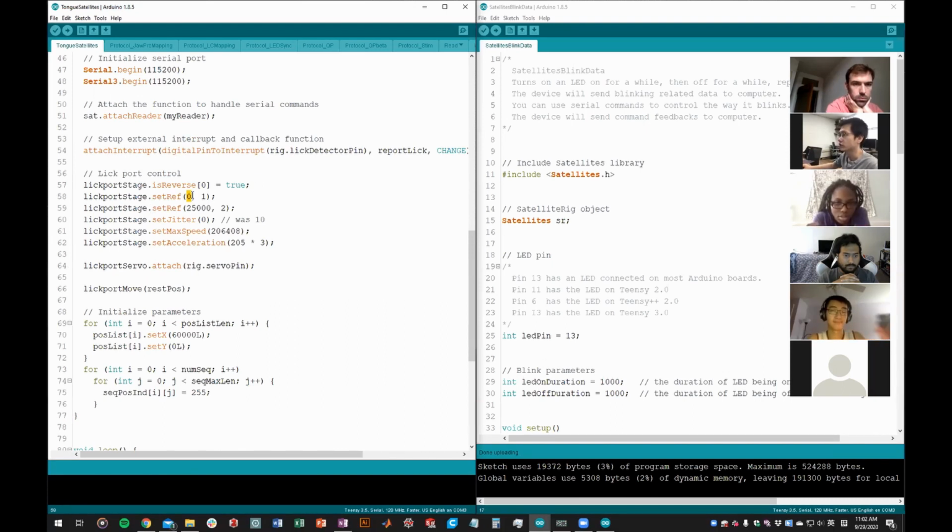Here is the reference coordinate for the first axis, which is the AP axis, and what is the reference position for the lateral axis, which is the second axis. So here, the second axis in our rig is 5 centimeters long, which is 50,000 microns. So I'm setting a reference halfway, meaning when we say 0, the lateral stage is at center. And when we say positive, it will go one way. We'll say negative, it will go the other way.